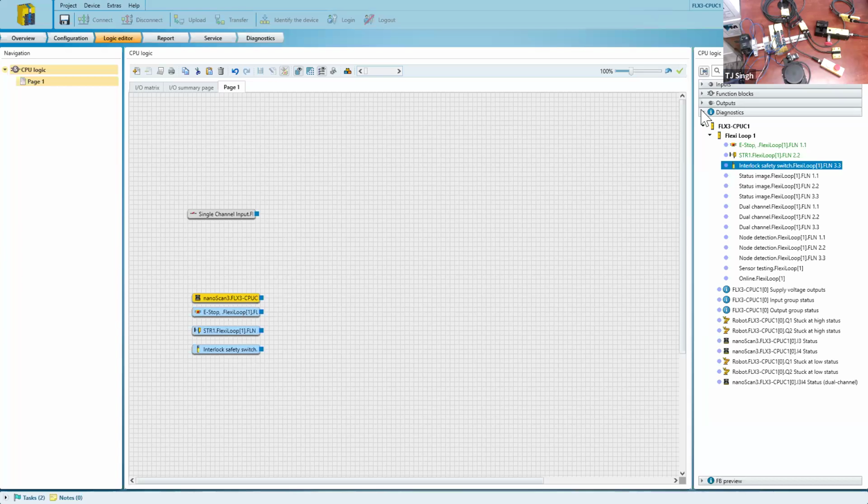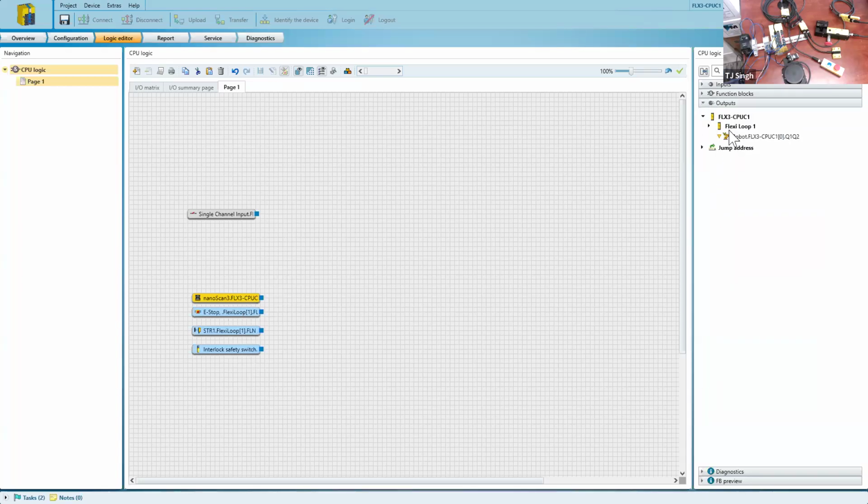And if you remember, I also had some outputs. What output I had? I had a lamp, if you remember, for the reset, right? For the reset, I had the lamp here to turn on the light when a reset is required. And I also had the interlock where I will send a signal to it to unlock the system. And lastly, I had the safety relay, which is represented here by like a robot output. And that's all the IOs that I have.